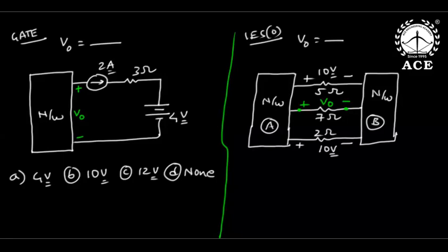Everybody listen now. Here I need V naught, the voltage across this box. If you see, there is a current source in series to all these elements. This is 3 twos are 6 volts, and this is 6 volts and 4 volts. Until here I can say it is 10 volts because 6 plus 4, 10, KVL satisfied. But without knowing the voltage across the current source, you cannot tell V naught. Please understand this meaning.